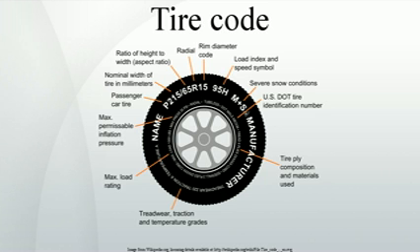Additional marks. There are numerous other markings on a typical tire. These may include M+S, or M&S, mud and snow: a tire that meets the Rubber Manufacturers Association, RMA, and Rubber Association of Canada, RAC, all-season tire definition. These are all-weather tires, with self-cleaning tread and above-average traction in muddy or very light snowy conditions, and for low ambient temperatures. Spike tires have an additional letter, E, M+SE.